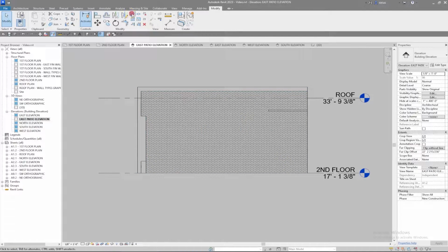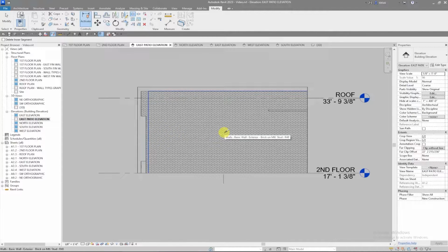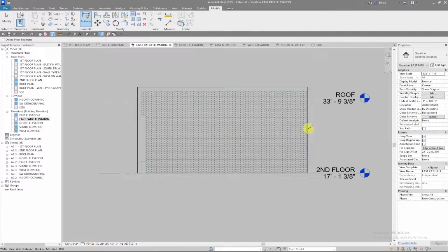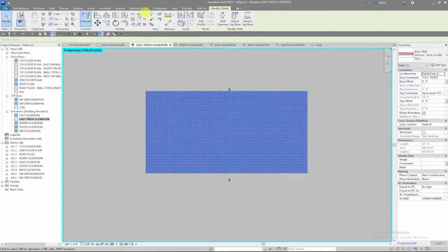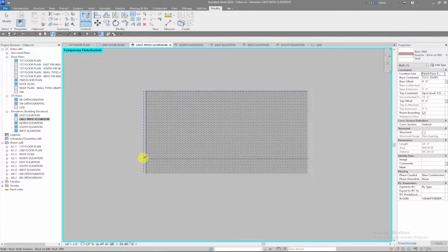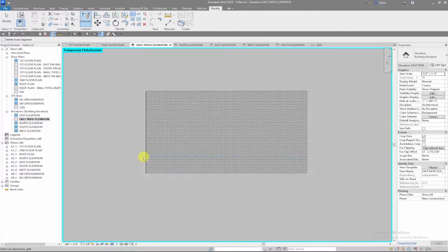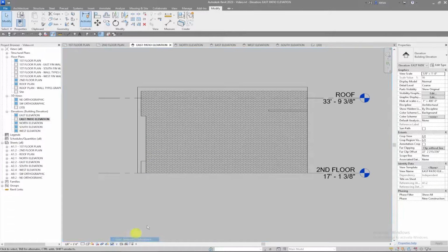So we'll use the split tool. Again, I'm just going to get a horizontal split. That was not a horizontal split. Let's see if I can do it from the other side. Okay, let's try this again. We'll isolate. Grab our split tool. So that isolate really helps us make these splits without editing the wrong wall. So we're going to isolate pretty much every time we do that.